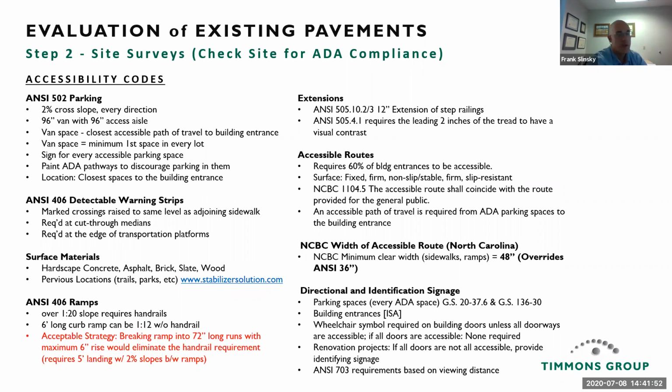So when you do a pavement evaluation, this is the ideal time to check for ADA compliance, especially if there's repairs being considered. You don't want to build back something that was wrong to begin with. So this way you look at your parking requirements for slopes, etc., detectable warning strips, surface materials, ramps, extensions, accessible routes, and all your directional and identification signage, like ADA signs, etc.